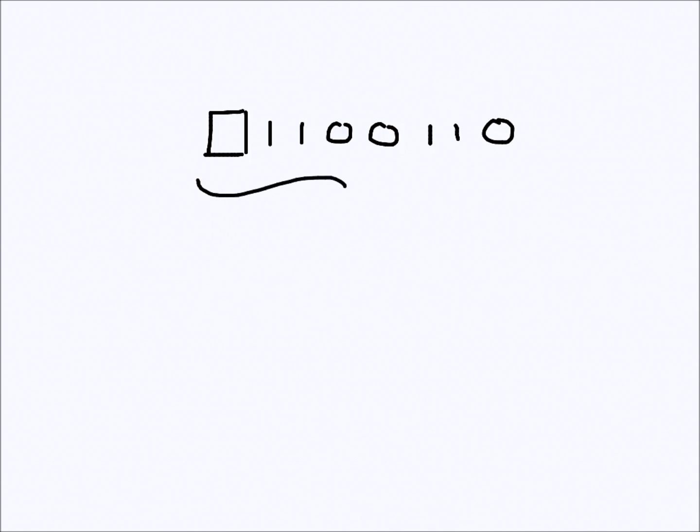Let's say an arbitrary ASCII code like that, 7-bit 110. So these are 7-bit ASCII code. The parity bit is another bit added here, and there can be two types of parities, even parity or odd parity. If we talk about even parity, this bit along with the other bits is transmitted together, so it will be an 8-bit whole: 7-bit data and 1-bit parity bit.